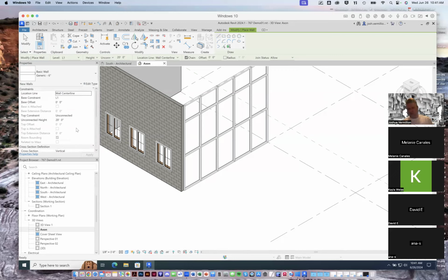It's unfortunate we're not really meeting in person, but when we do, I like to walk people around downtown or around campus, and we can take a look at different glazing systems because you'll see a variety, right? Curtain walls don't always have to have mullions. In fact, a lot of times for storefronts in urban areas now, the trend is to not have mullions. Sometimes you have glass mullions, or if you're not spanning too far, if the height isn't too much, you don't even need mullions at all.